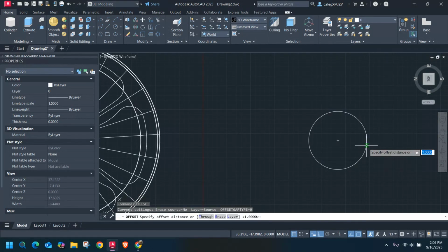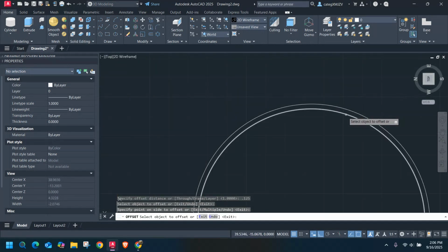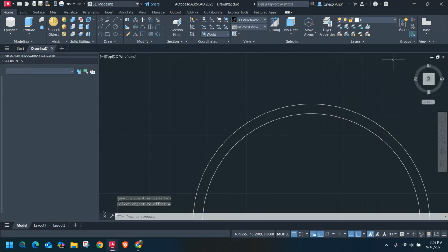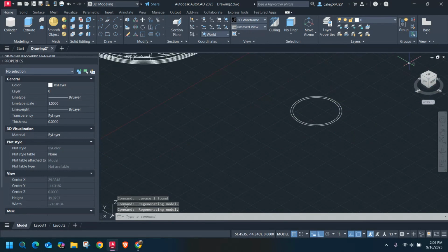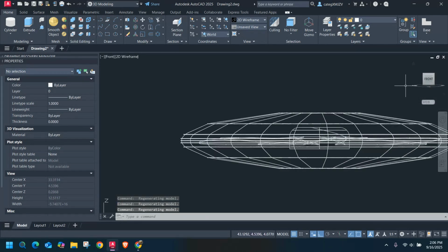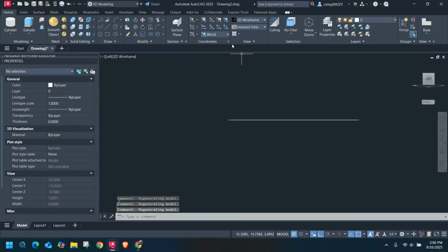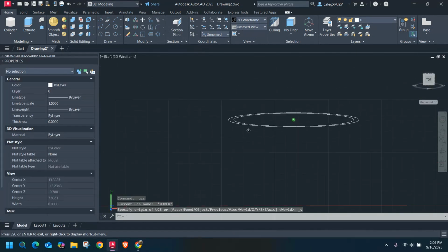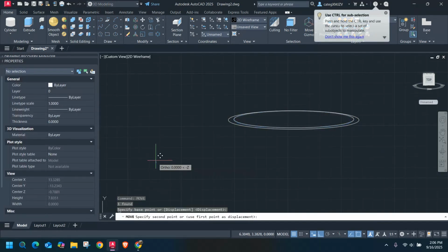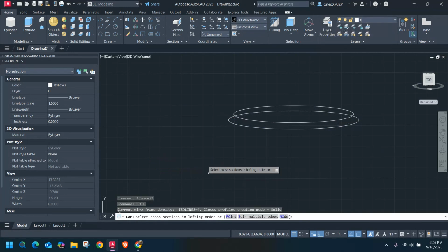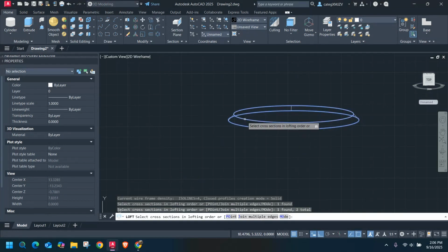And let's see, offset it. Doesn't need to be much. Okay. Maybe I want a little bit more, like that, right? And look at it from the side. Maybe this side so I can see it, yeah. Change your view and bring this up. We're gonna move it along the upper plane. And then you can just do a loft if you want and just loft that into place, right?